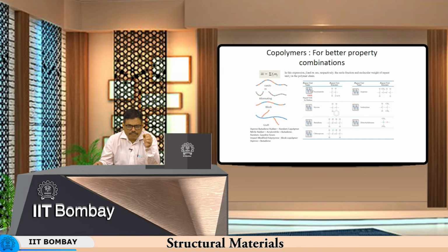Similarly, if it's a regular block, 4 or 5 atoms of one, 5 of the other, etc., now you have this polymeric chain which has been generated with definite repeating patterns of each of these constituent chain configurations. So when two chains have to come together and arrange themselves in a regular array of atoms, it becomes easier because everything is blockwise defined, and blockwise alignment also becomes very practicable and simple.